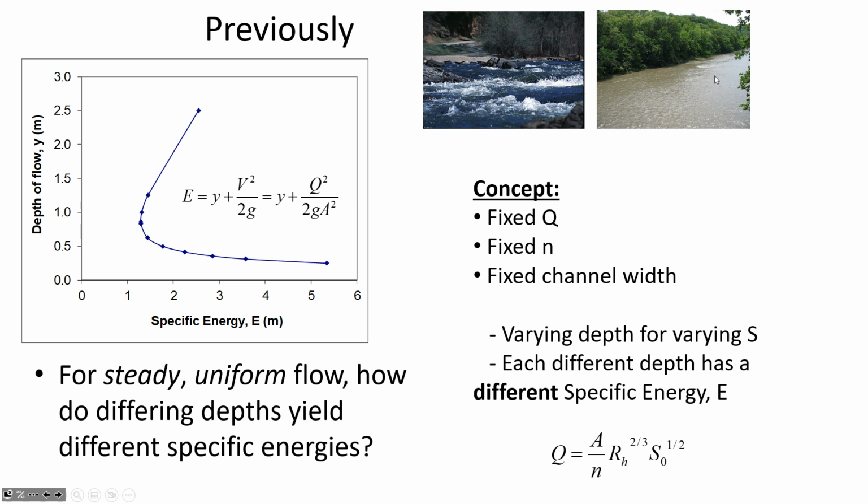A lot of the rivers and streams around here have relatively slow moving velocities, and we need to be able to analyze whether conditions are down here in the supercritical range or in the subcritical range, because when we encounter some sort of obstacle, the amount of energy that's lost is going to affect the flow depth differently depending on whether the before condition was supercritical or subcritical.